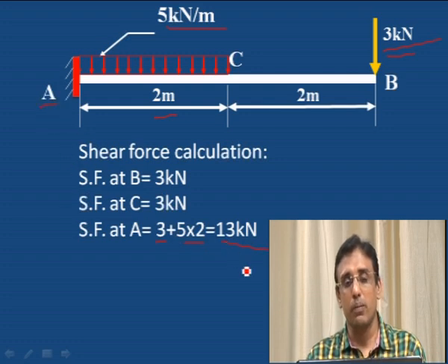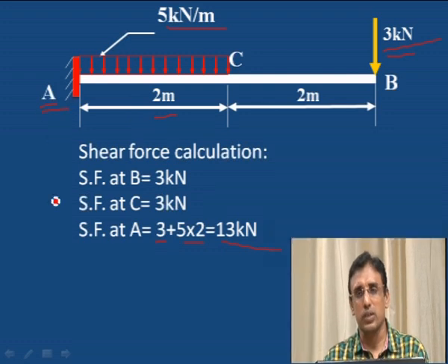Whatever problem we are solving, we can observe that in all cases shear force is maximum at the fixed end. That is what you have to observe. That is because all the loads are added together, and we get the maximum shear force at the fixed end.